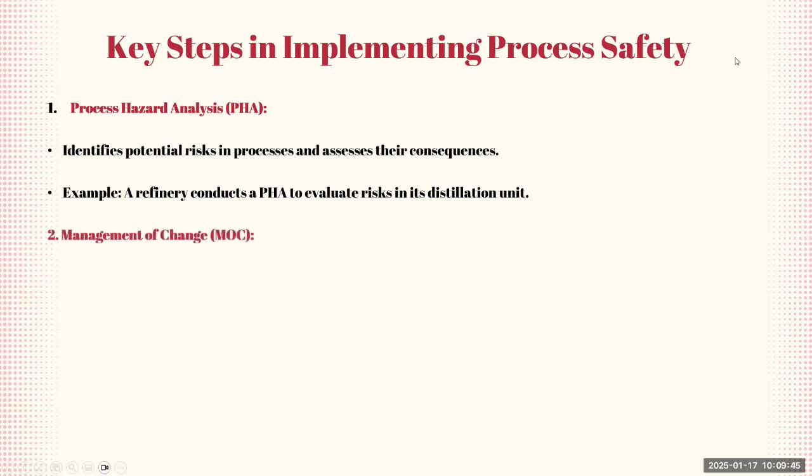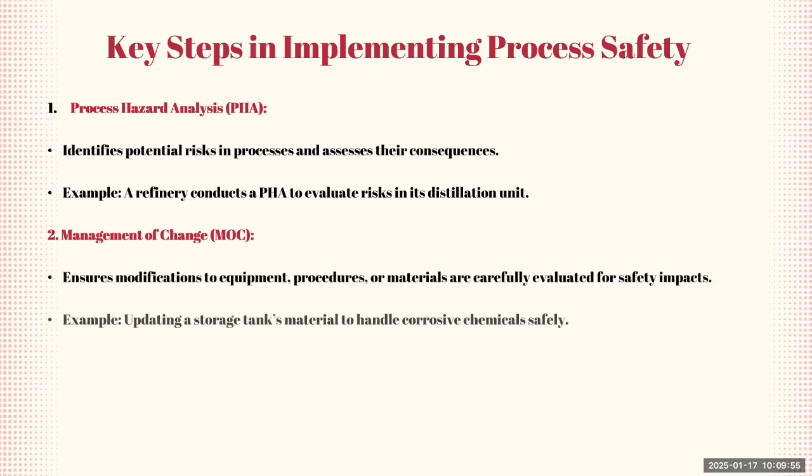Then it's the management of change. Management of change, believe it or not, is really, really important. And most of the time, it's what leads to failure of our equipment. Because when a modification is done to an equipment, we also need to update how we protect this equipment. Because let's say that this vessel is designed for 10 bar, but then 10 years later, another engineer comes and says, okay, I would like to operate at greater than 10 bar.